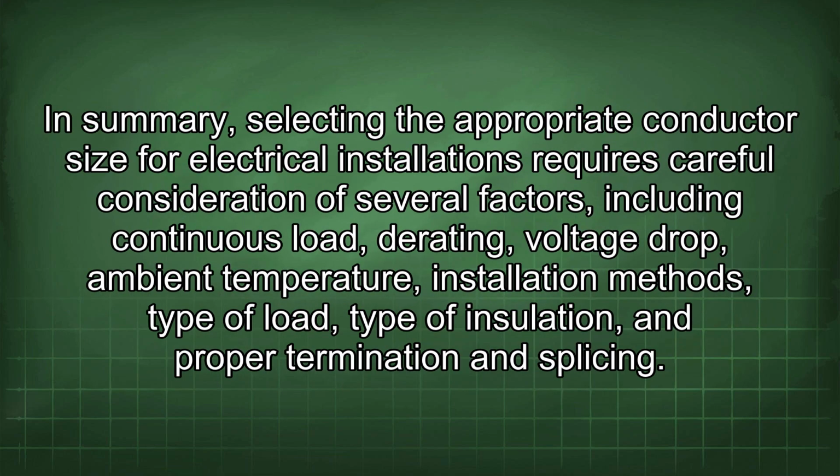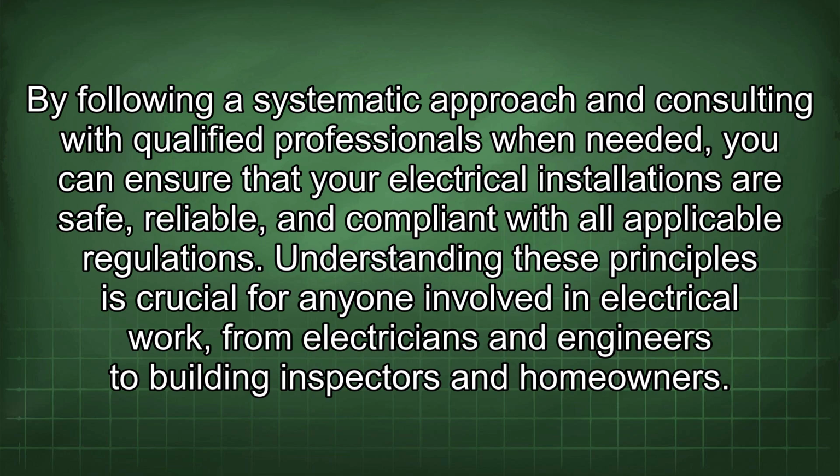In summary, selecting the appropriate conductor size for electrical installations requires careful consideration of several factors, including continuous load, derating, voltage drop, ambient temperature, installation methods, type of load, type of insulation, and proper termination and splicing. By following a systematic approach and consulting with qualified professionals when needed, you can ensure that your electrical installations are safe, reliable, and compliant with all applicable regulations.